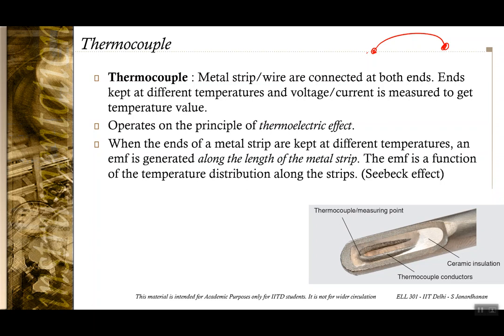It uses the principle of the Seebeck effect or the thermoelectric effect, which says that when the ends of a metal strip are kept at different temperatures, an EMF is generated along the length of this metal strip, and this EMF is a function of the difference in the temperature, or of the temperature distribution along the metal strip.